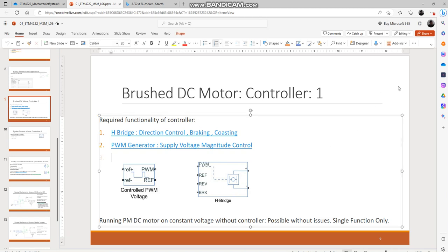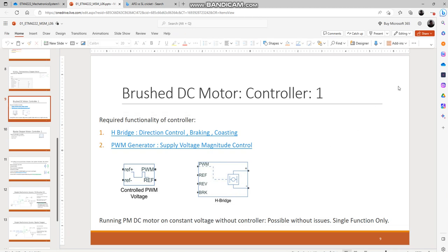So for our modeling purposes of this exercise, we won't be using H bridges and control PWM voltages, since we are taking a look at what would happen once a 12-volt DC power supply is used. However, in 99% of actual cases, you will be needing H bridges and control PWMs provided from a microcontroller or 555 timer arrangement.